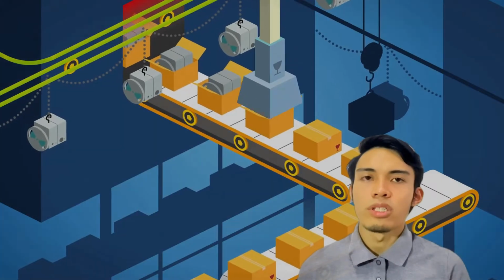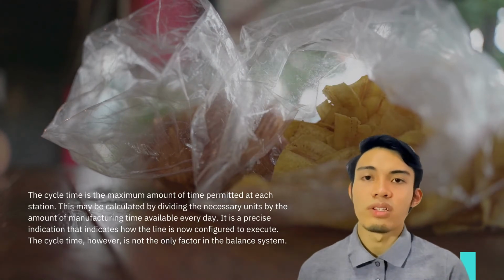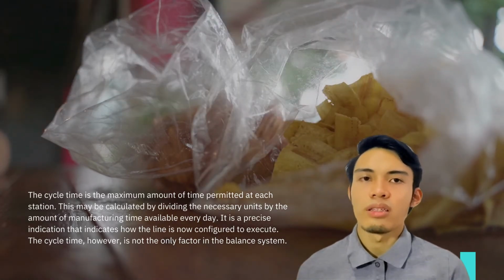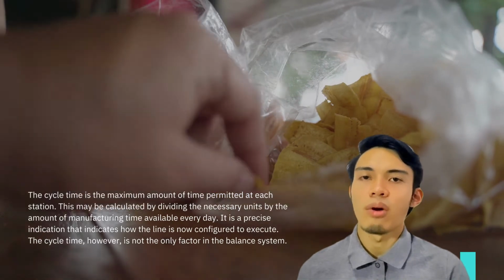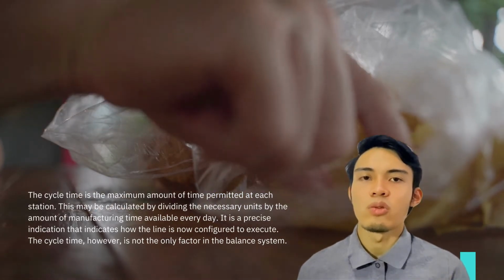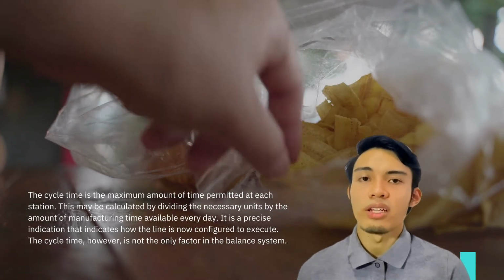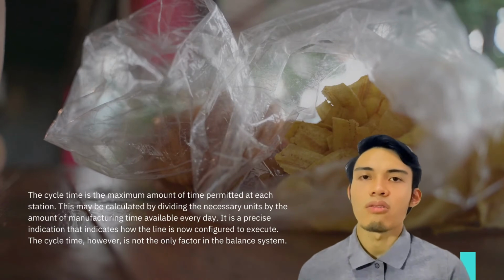The cycle time, which may be defined as the maximum amount of time permitted at each station, is the first consideration. This may be calculated by dividing the necessary units by the amount of manufacturing time available every day. This is the period in minutes between two goods leaving the production line at the same time. It is a precise indication of how the line is currently configured to execute it.